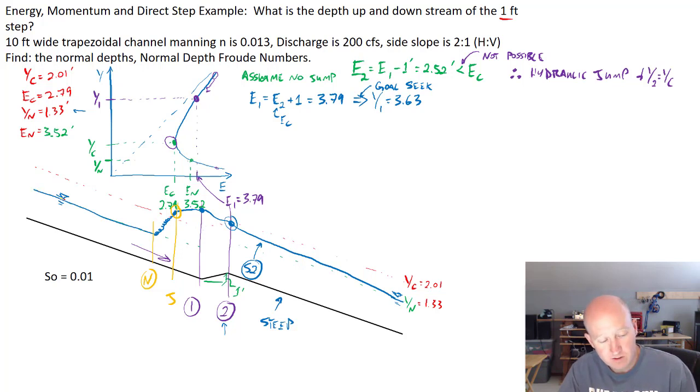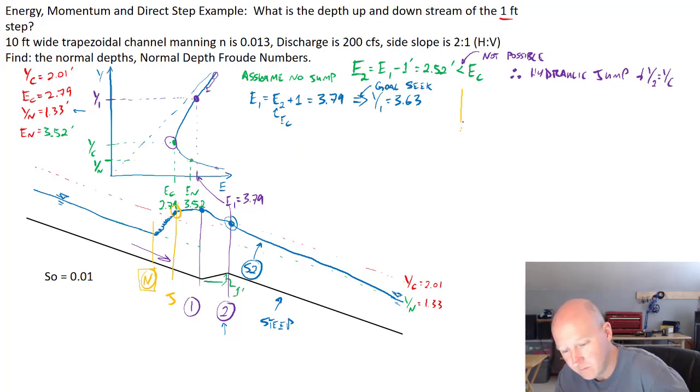So the water is racing along, and then bam, it hits the hydraulic jump. And from that point, it's going to jump from this specific force that corresponds with normal depth. It's going to jump to the specific force, which is the same, which is called the conjugate depth. And so if we wanted to look at a plot of specific force,